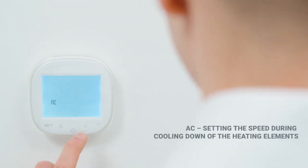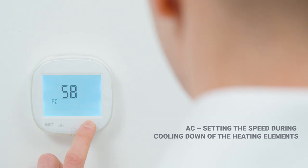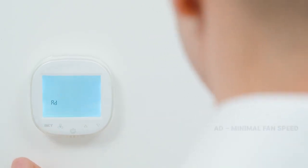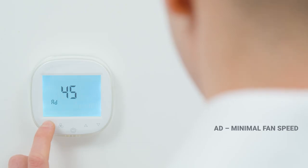Function AC: fan speed settings at the time of cooling down the heating elements. We can set values from 45 to 100%. Function AD: this is information about the minimum fan speed, without the possibility of changing it.